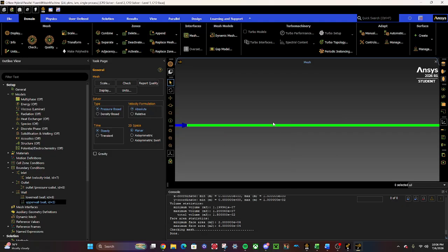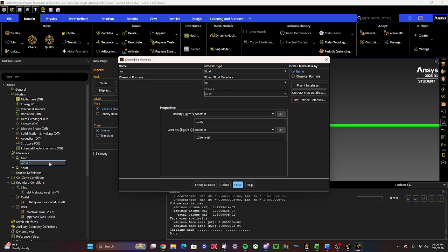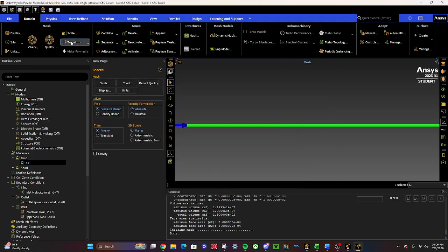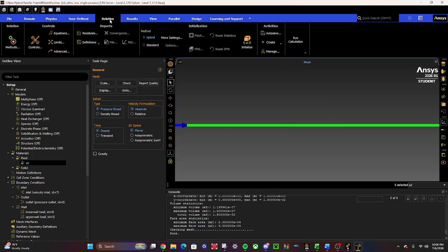And that should set up the experimental parts. We're going to also want to go to our materials of the fluid, the air, and we can change these. We're going to want a density of 1. We're going to do a viscosity of 0.01 here. That should help in creating this. Hopefully that's saved.